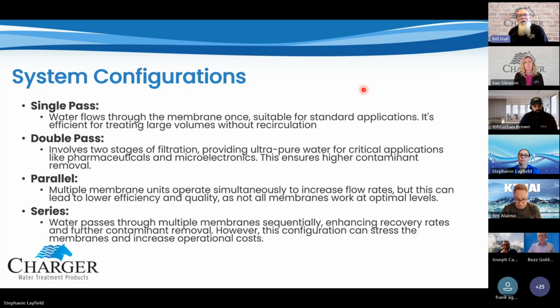It's hard to say whether a membrane's going to last a year or so, but if you've got that high hardness and you're using that RO a lot, like you should be, you may have to change that membrane once a year. It may be part of your annual maintenance. Fortunately, on point-of-use ROs, the membranes are fairly inexpensive, not that big a deal. Commercial ROs, a whole different ballgame.